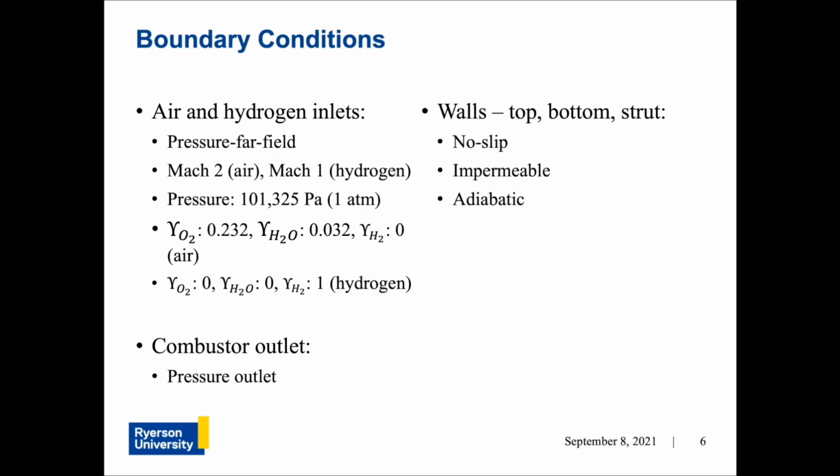A no-slip condition is applied to all solid walls, inclusive of combustor top and bottom walls, and all strut sides and base. The no-slip condition specifies that fluid layers adjacent to the walls are of zero velocity, both parallel and normal to the surface. This is applicable in the viscous models, cases 2, 3, and 4, which should induce velocity and thermal boundary layers. The walls also do not permit heat transfer or movement of particles through them, thus making the control volume only the interior flow.